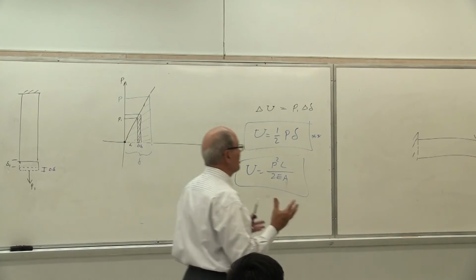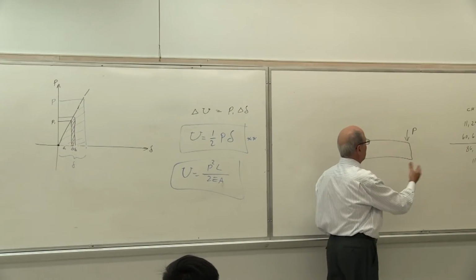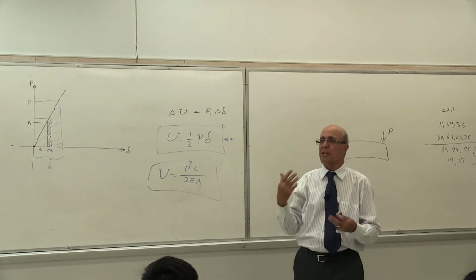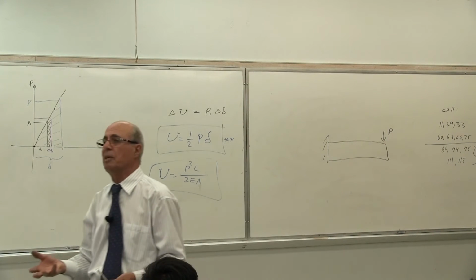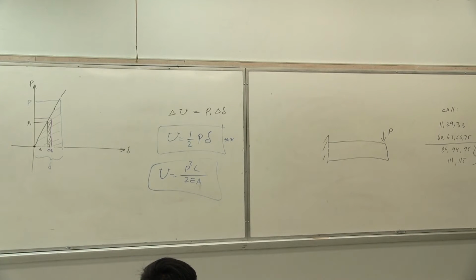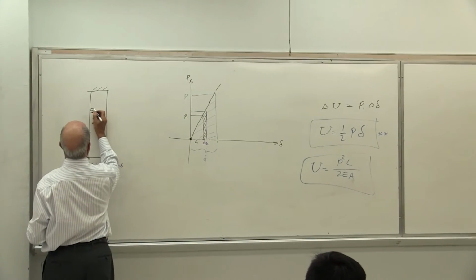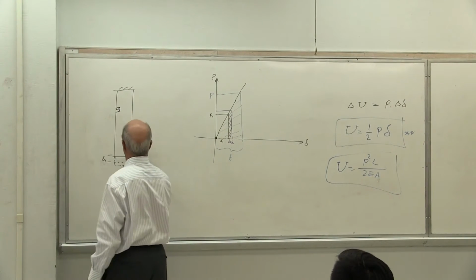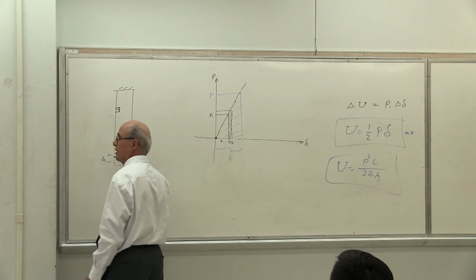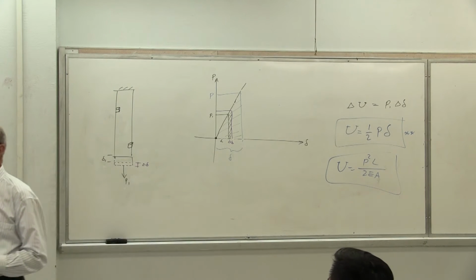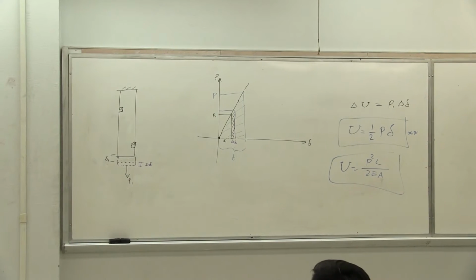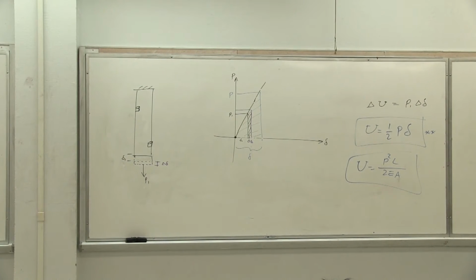Therefore, the distribution of strain energy is not uniform, because it depends on the sigma or on the strain. The difference here is everything is constant. In other words, if I use 1 cubic inch of material here and 1 cubic inch of material here, both give me the same amount of energy because they have the same sigma and the same epsilon. Is that understood? Because if you don't understand that, I cannot go to the next phase of the operation.